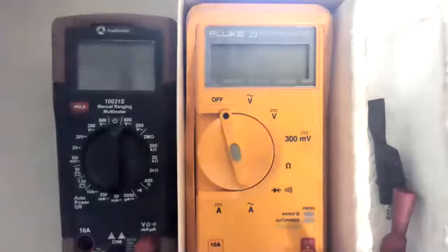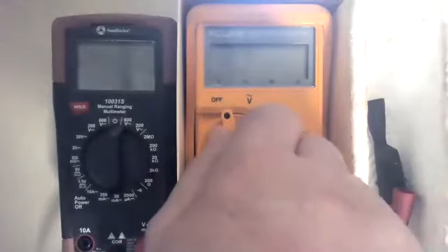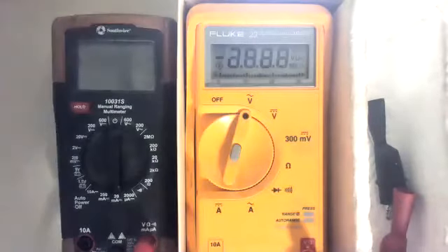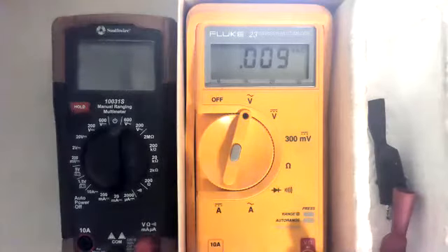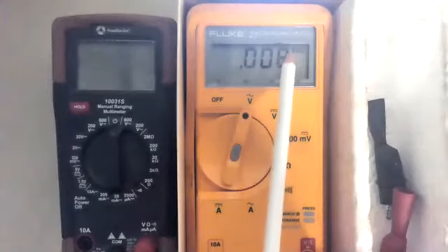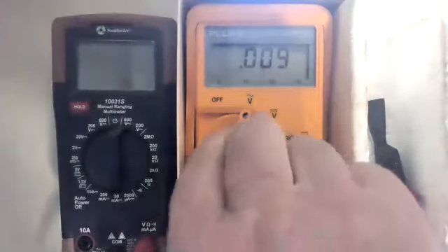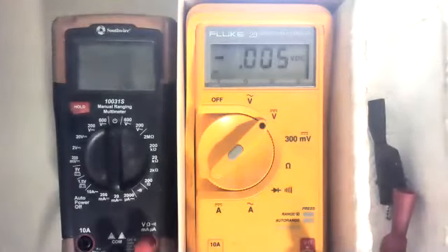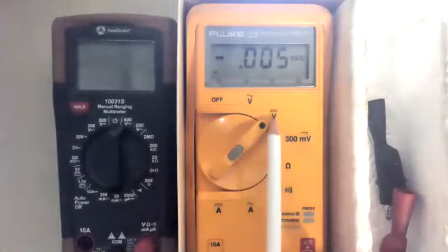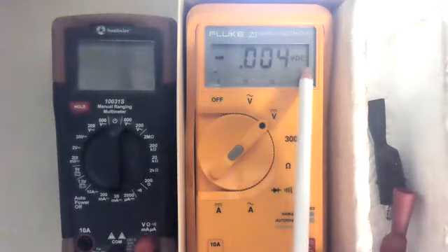In here, you can see there's that little wavy line. If you wanted to measure the voltage coming out of a plug at your house, you would measure here at AC. You can see the little VAC up here, voltage, alternating current. Now, if you wanted to measure like your car battery or flashlight battery or a 9-volt battery, there you go. We got the V with a straight line with a dotted line here. And there you go. You have voltage, direct current right there on the screen.